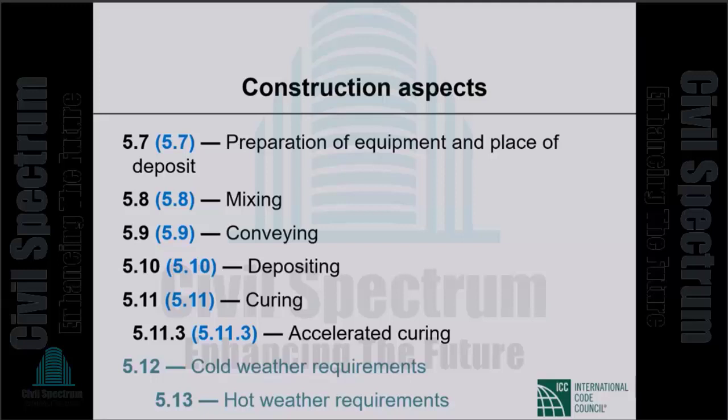And then depositing, how do you put it in place from the head of the pump to where the concrete ultimately belongs? And then after you have placed the concrete, curing is absolutely critical. There is nothing more important than curing of the concrete. You cannot let the concrete dry too quickly. That will lead to cracking and weaknesses.